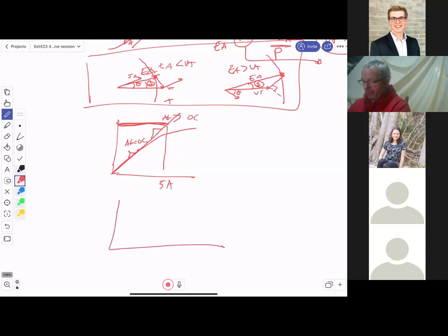So remember, we have 3 curves. We have the open circuit characteristic. And let me draw in a separate color, we have the air gap line. And the air gap line is always going to be sort of linear. And then we have the load characteristic, and that's where we're plotting IA. In all cases, this is IF. So you can tell when you're saturated.